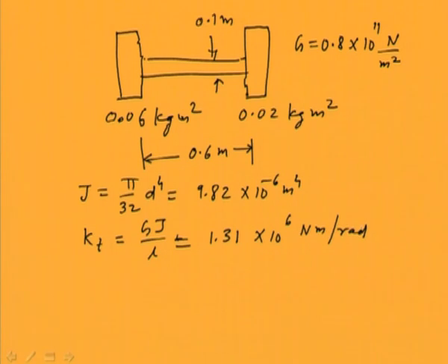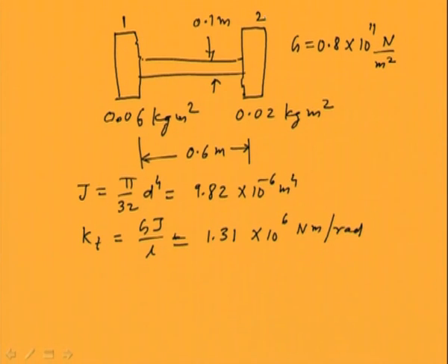Now let us come to the transfer matrix, in which we have two stations, station 1 and 2, that is 2 disks are there, and the state vector of right of one disk can be written as, with state vector at 0th node, 0th station is here, station 1 is here, and this is related with only point matrix, because between 0 station and 1 only disk is there.